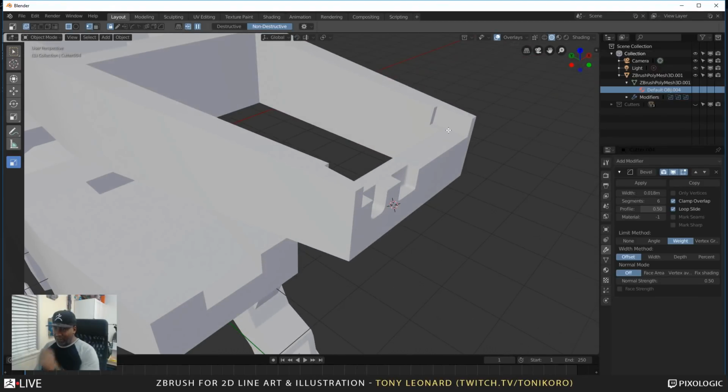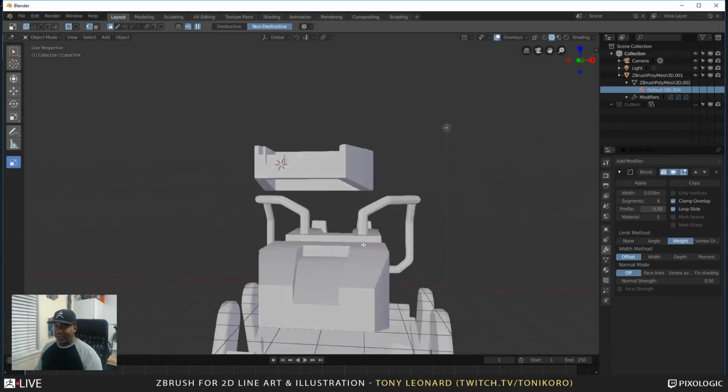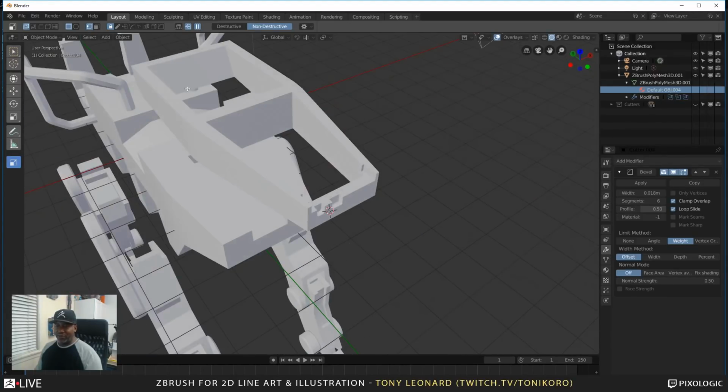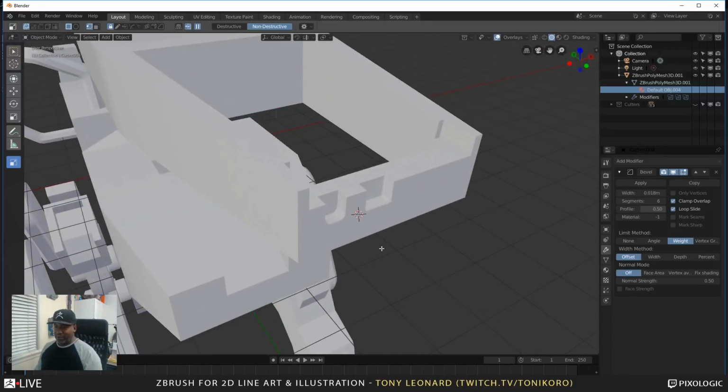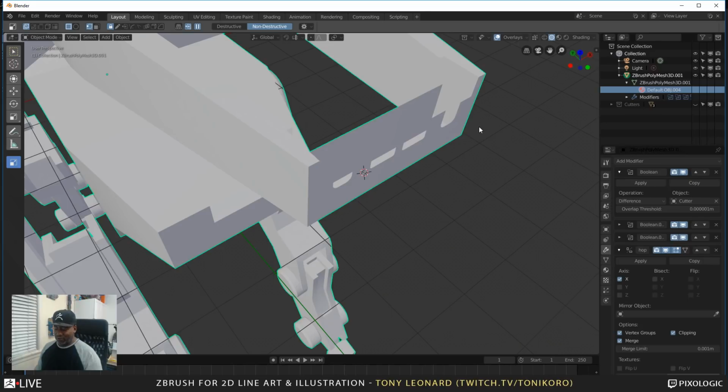And so you can imagine, as I sit here, I would just keep coming in here and start doing some cuts. I'm only working on one side of things, but here's the trick of it. If I select this, it would probably be better if these were applied, but even if not, I can still move those over to symmetry, because they're still live, right? But what I'll need to do is hit Alt, and I don't need to change the scale or apply scale just yet, but I can skip it over to the other side.